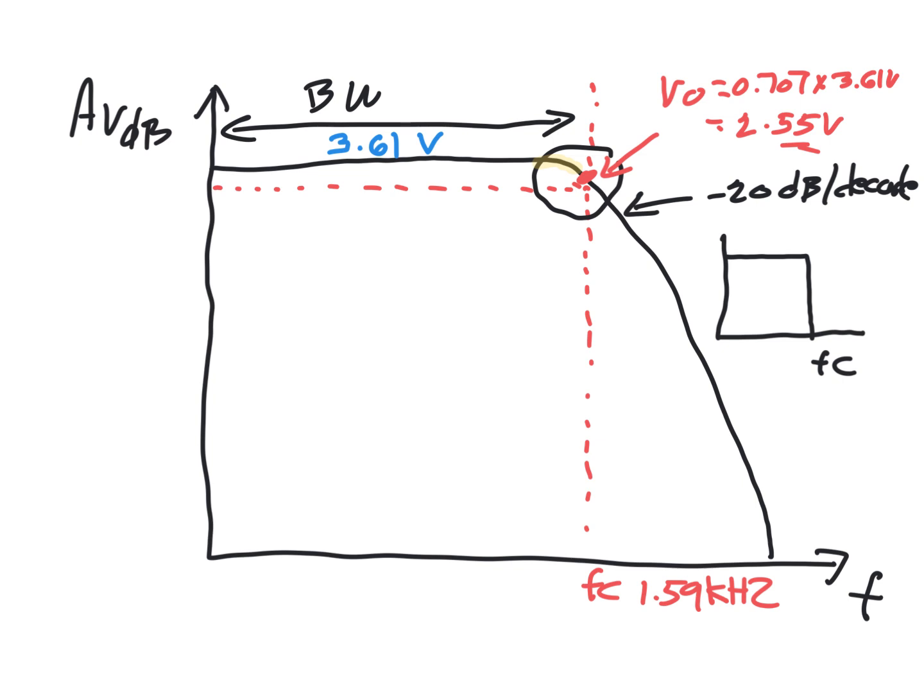In the lab experiments, I think the passband gain is 5, right? So if you take the 5 times the 0.707, that's 3.5. You can easily then tell that when your output voltage is 3.5 volts, you're at the critical frequency. So it's very easy to experimentally determine that.